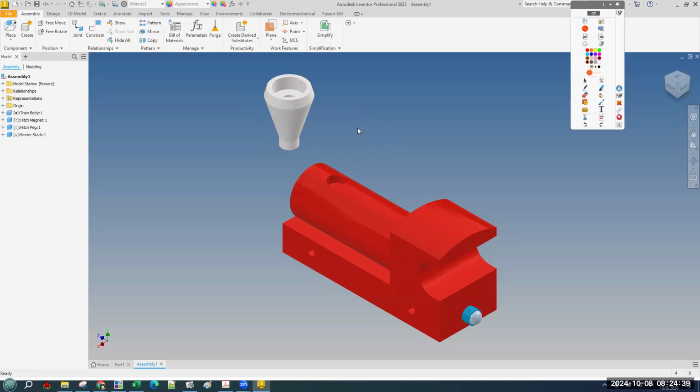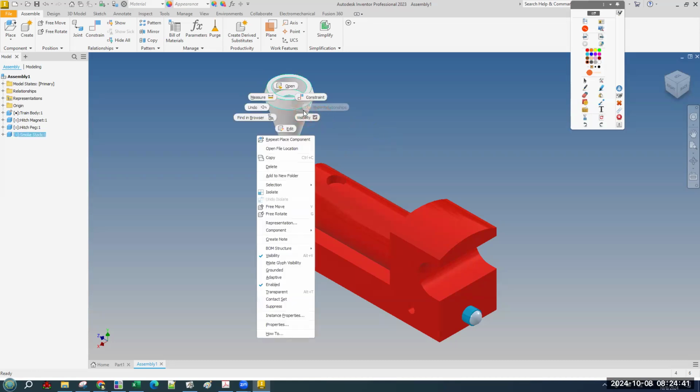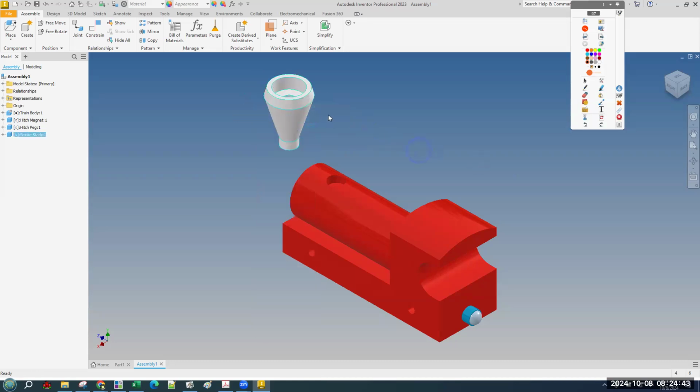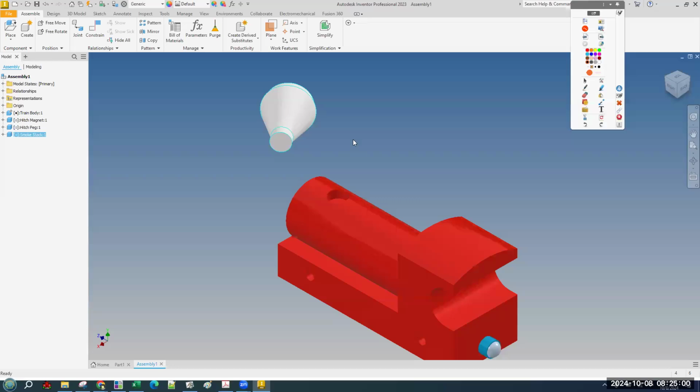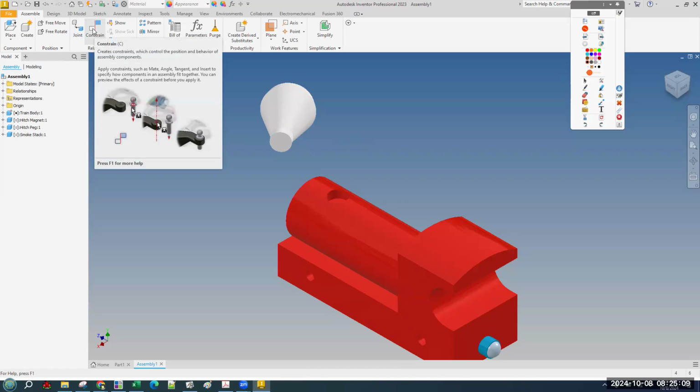They're all going to be pointed the correct direction, but you can orbit things around inside of the assembly, but you don't really need to, because even if this came in sideways like this, if it was made sideways, the program, I almost said the game, the program would guess that's how you want it. But it doesn't really matter because constraining things, just like constraining dimensions in a sketch, puts it in the right place, but also locks it in the right place.